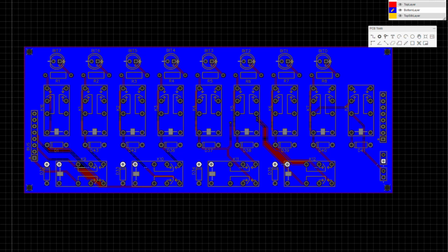These relays down here are basically gatekeepers. It stops power on these being put out onto the bus unless the set is enabled, which is one of these ones over here, that one. So when set is enabled, all of these can then pass through and either set these or allow the power out to the bus for reading it. And then you have a reset, which activates this one, which cuts the power to all these.